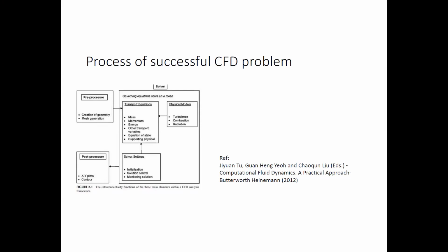For the pre-processing, yes, the volume was a little bit low. The pre-processing means the creation of the geometry and the mesh generation. Once we generate the mesh, we define the domain, which is called the computational domain. This is the pre-processing. For the solution, there are the equations that we are going to solve, and besides